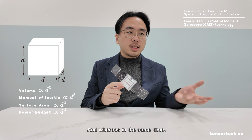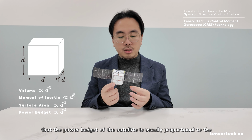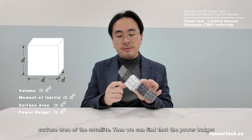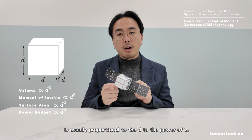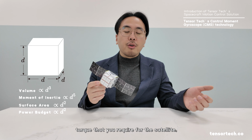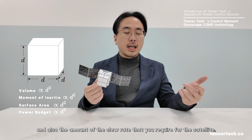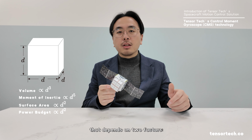Whereas at the same time, the power budget of the satellite is usually proportional to the surface area of the satellite, so we can find that the power budget is proportional to d to the power of 2. That gives us an interesting insight: the amount of torque you require for the satellite, and the amount of slew rate you require, meaning how fast you are going to steer the satellite, depends on two factors.